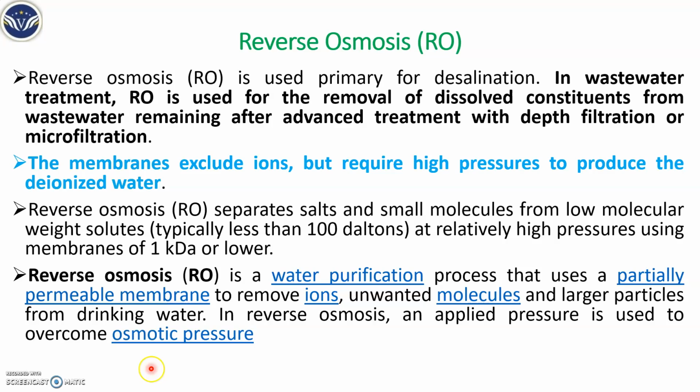We are now going to see the reverse osmosis process. The reverse osmosis process has a great advantage compared to depth filtration. Depth filtration is the slow sand filter, rapid sand filter and pressure filter. The filter media depth there is larger, in centimeters, say 90 to 110, 60 to 80 centimeters. Compared to that, these are very much smaller.